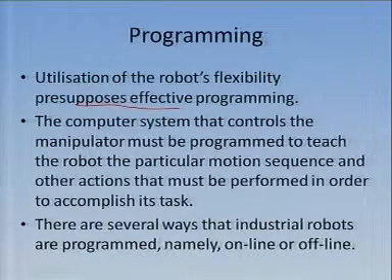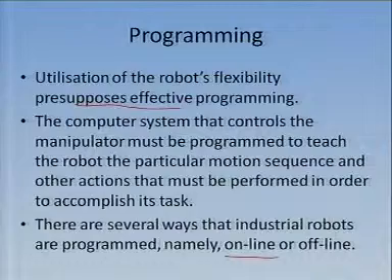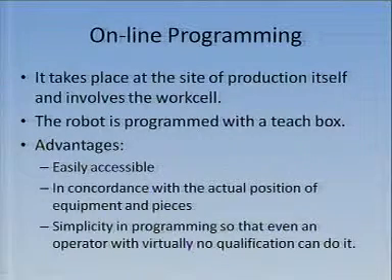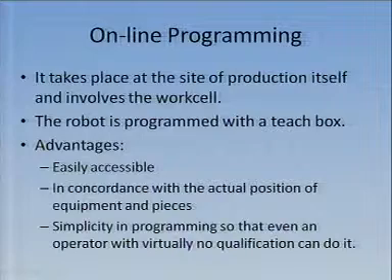Okay. Now, there are several ways to do the programming. Two of them are mainly classified as online programming and offline programming. Okay. So, online programming takes place at the site of the production itself. It has a teach pendant.